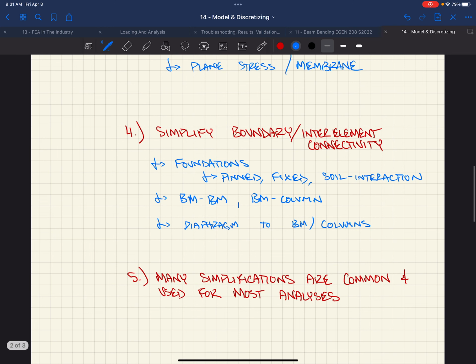To our beams and our columns, we have this guy right here. This is our building. We have a diaphragm that sits here. We got a lateral load that's on it. How is this diaphragm interconnected to all of these beams? And we know that it's only connected at nodes. Exactly, I'm so proud. Nodes. And if there's no nodes on this beam, that diaphragm is not connected to this beam.